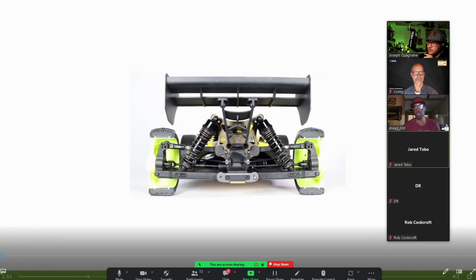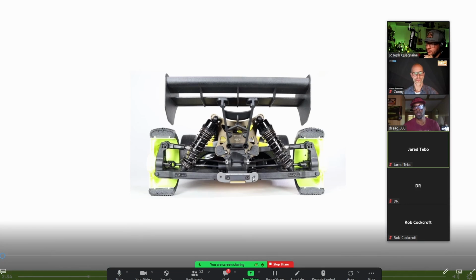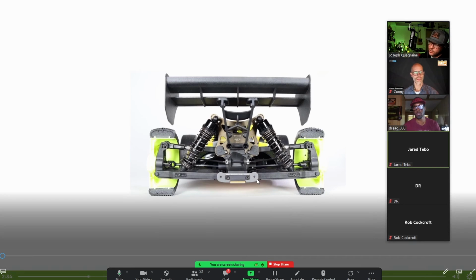Most drivers won't, because you have more initial grip. So if you push it beyond that, then your rear will break loose suddenly. So you have more initial grip, you have a higher peak of traction, but you also lose that faster. So if that's your problem, then lowering the arm would actually be better, because you have more overall traction at